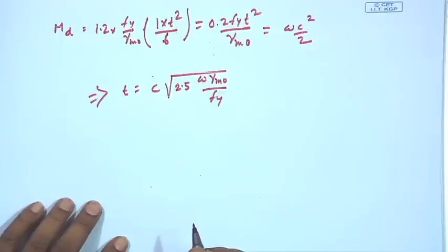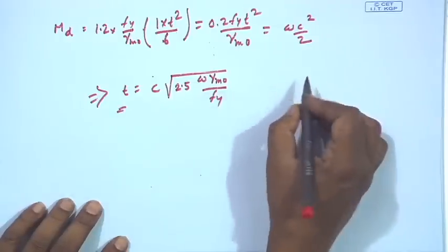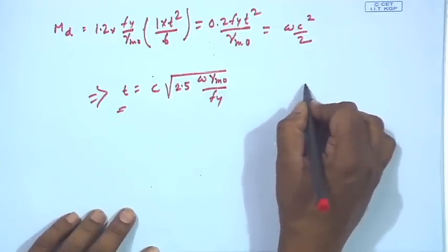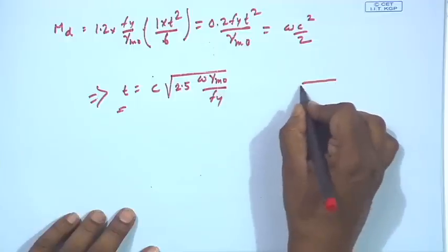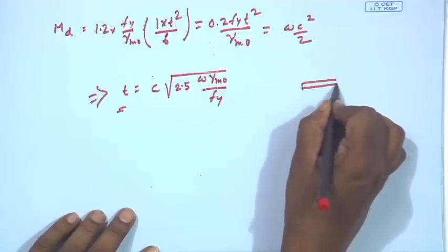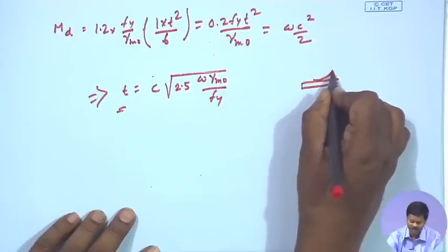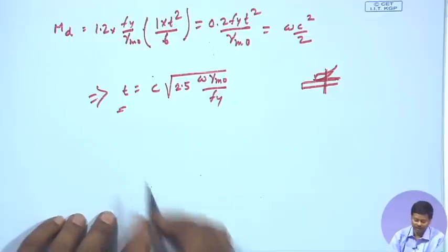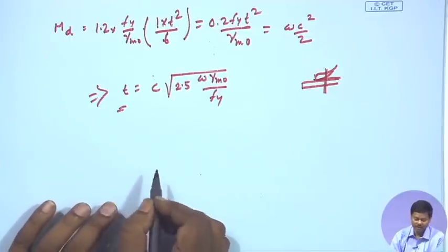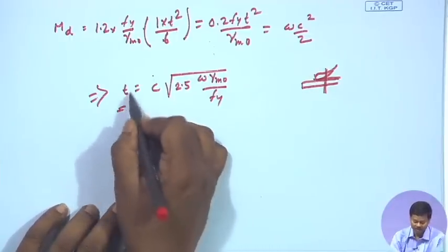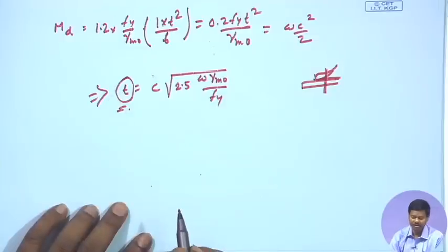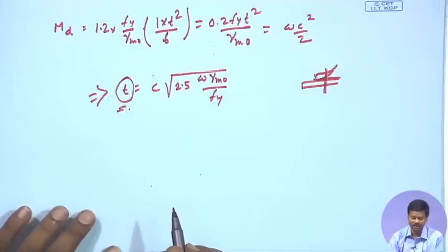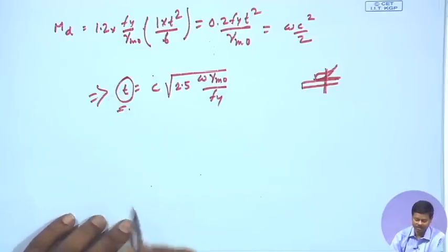right. So, what is T? T is the thickness of the base plate plus the Gusset angle, that means the summation of thickness of the base plate and the Gusset angle. So, this will be the thickness. So, base plate thickness will be total thickness whatever we are getting minus the Gusset angle thickness, then we can find out the base plate thickness.